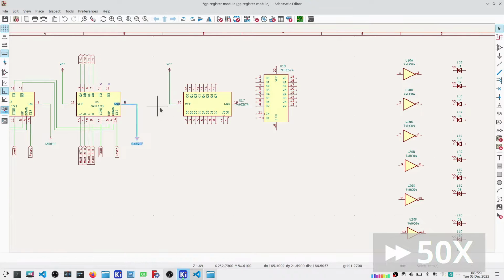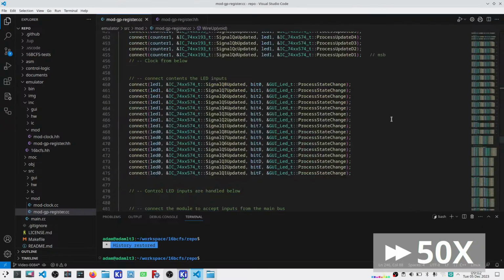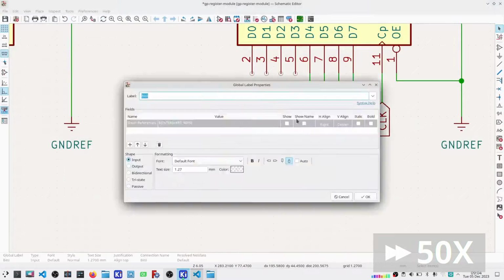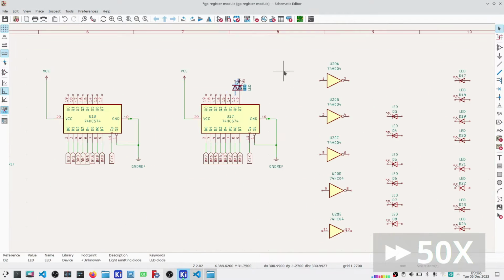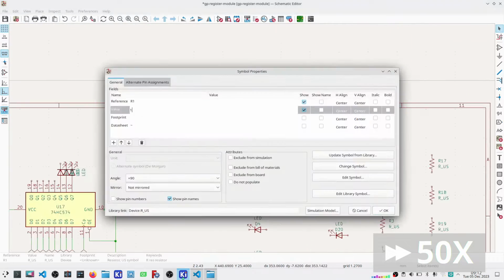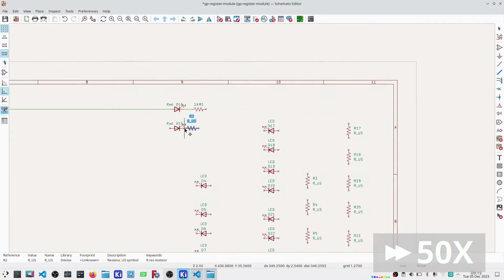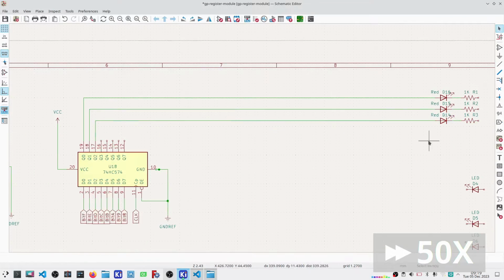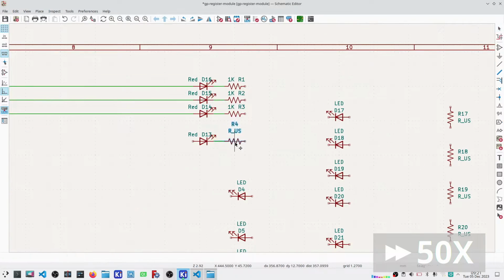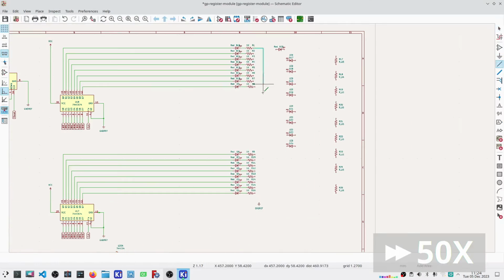The next thing on the list is to connect up the latches which control the outputs for the contents LEDs. Now, it needs to be latched at the same time as everything else, so there is a clock that needs to be brought into that, but output is always on, so that's going to get tied low. The LEDs are going to get hooked up, and then of course through a resistor to ground. And that's a little bit fussy because of space constraints. So I do spend a little bit of time working on that, trying to get that all sorted out.